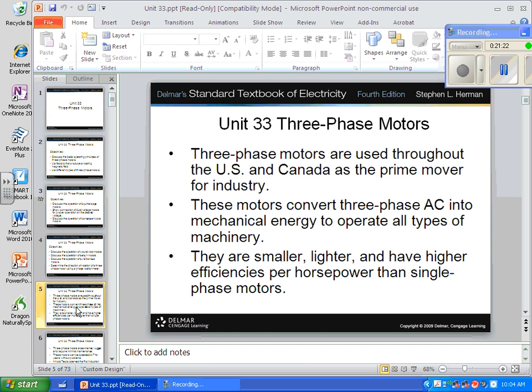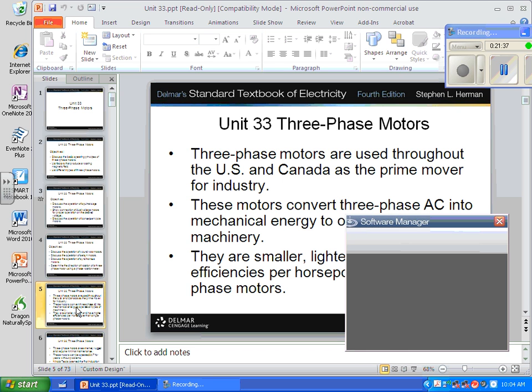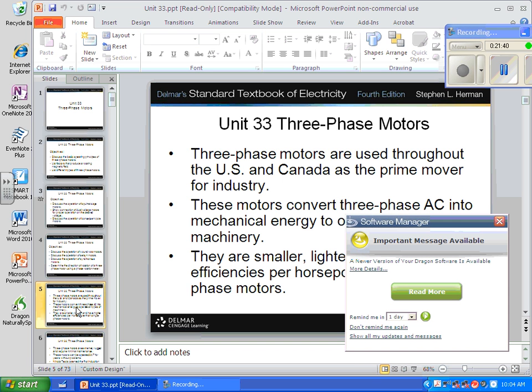Three-phase power will have one of two rotation schemes. You either call it ABC or BAC. ABC is, let's call that forward for a moment. Incoming power can have a rotational aspect to it. So if you hook up equipment that was connected to ABC, you take it off, you put it back on, and you connect it back BCA, it's going to run backwards, right? Well, there are worse things that can happen.